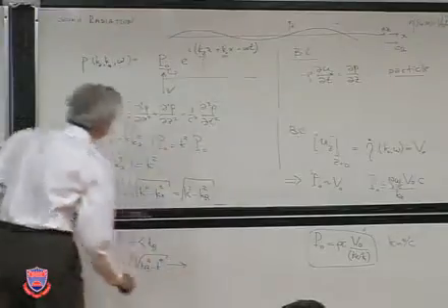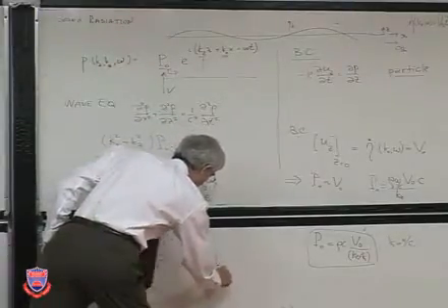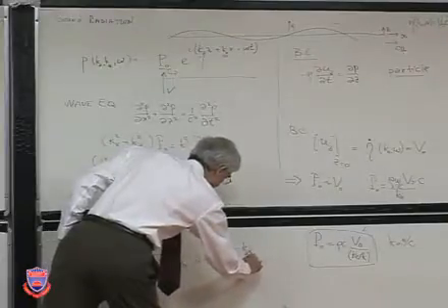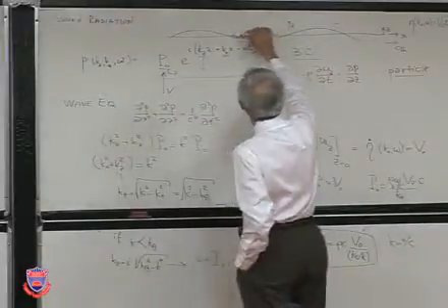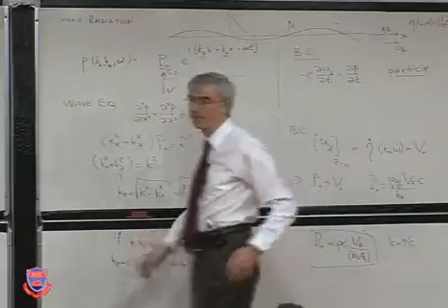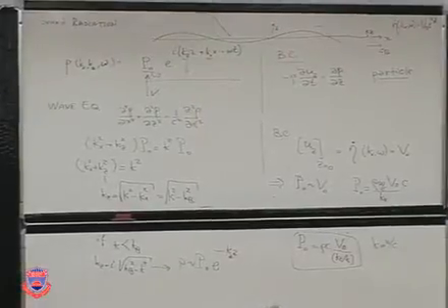And what does that do? That gives us a pressure with e to the minus kz z. So as you go away from the plate, the amplitude will just decrease immediately. So sound doesn't propagate, energy doesn't propagate to the far field.